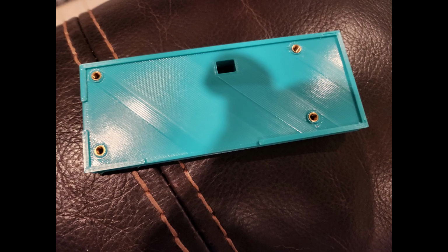Unfortunately, I didn't take a video at the time, but I used these 4 heat inserts that I picked up from ePaper to make the connection a lot more stable. So I just put them into the holes that I have in the 3D print and then push down with my soldering iron on them to get them into place. And that pretty much was the extent of the setup. Just 4 20mm M3 screws holding it directly to the device.